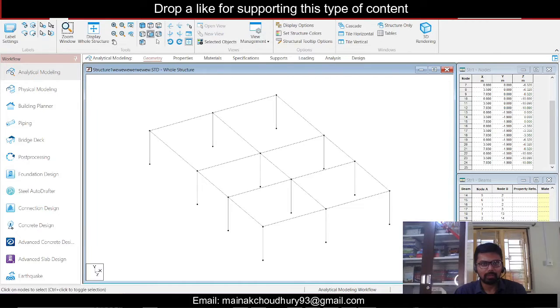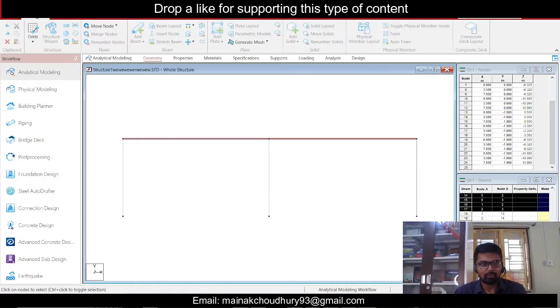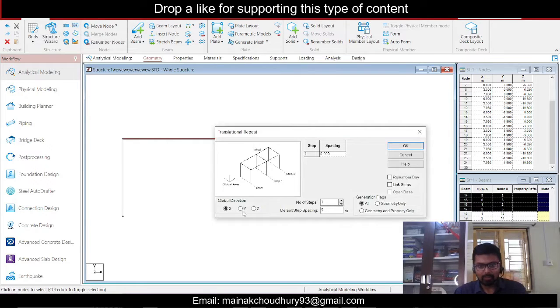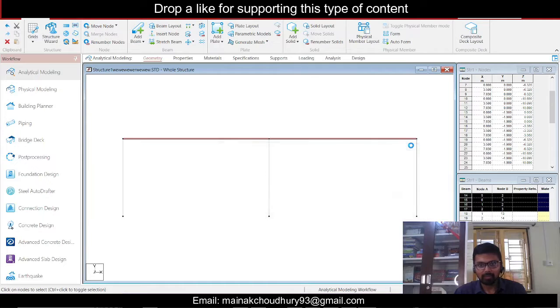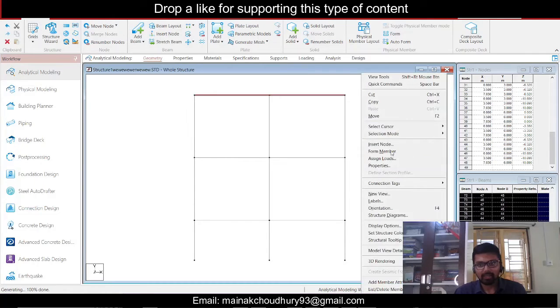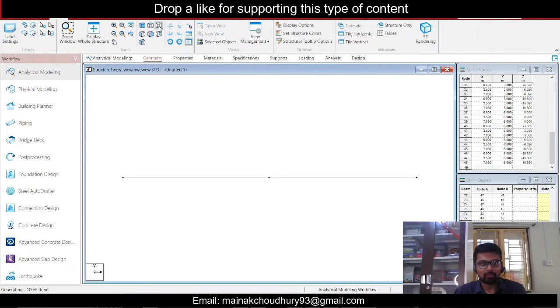Now we will move on to the front view. Click on escape to move back to the normal beam cursor, and select this. After selecting this, we'll go to geometry and use the translation repeat option, for the y direction, and we'll give 3 meters and 2 as the number of floors, then click on link steps and click on OK. The topmost floor has some options, so we'll select this, right click and click on new view. Click on OK, then go to view and go to top view.